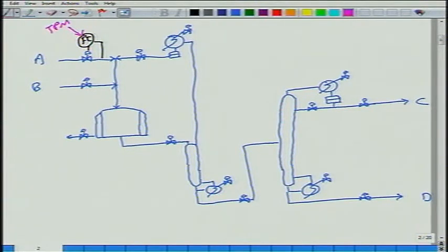Okay. Amount of B that must come in must be in ratio with A. So, I say, okay, well, and there is a flow controller here, this is setting the set point here. As before, the composition set point for this comes from here, limiting reactant concentration comes from here.